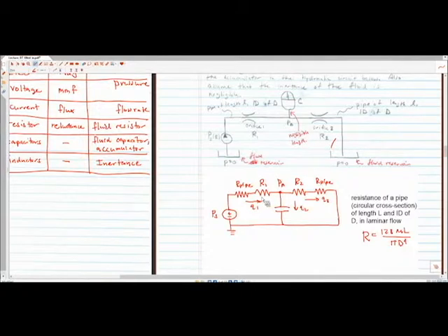So that, I would say, is from the perspective of mapping out what the pressure is at any point in this fluid flow, right? The way we look at it in this class is called lumped parameter analysis. This would be P1, and this would be P2. We're essentially ignoring everything that happens in this region, and we're calling it a resistor. And so the pressure will be lower at P2 than P1 as long as this cross section stays the same, because we had something with a resistance associated with it, like an electrical circuit.